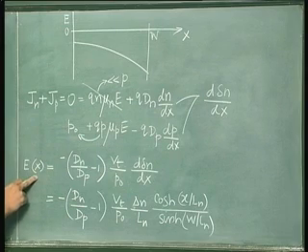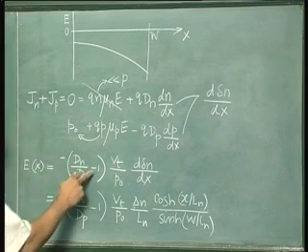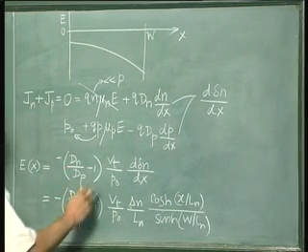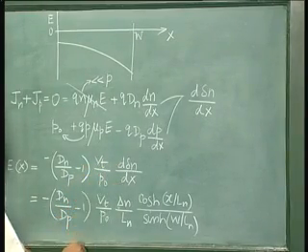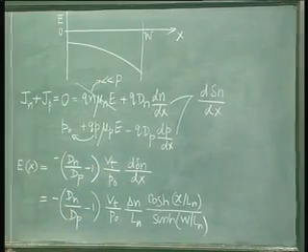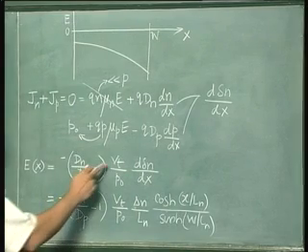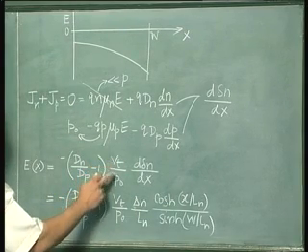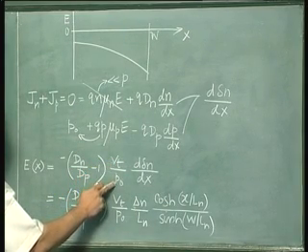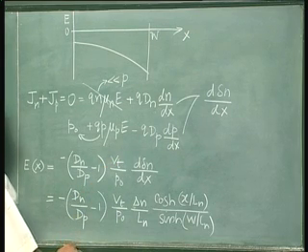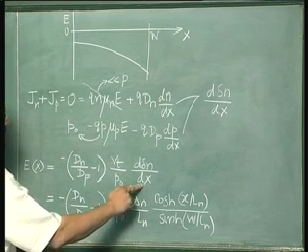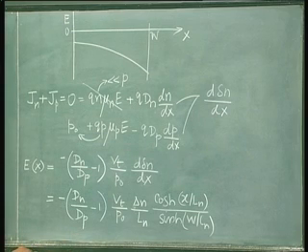Ex is equal to (dN by dP minus 1) in brackets into Vt by P naught into d delta N by dx. See that dimensionally this equation is electric field. Vt is volts, and P naught and delta N have the same dimension, so they cancel, and dx is centimeters, so volts per centimeter. Okay, so this is electric field.